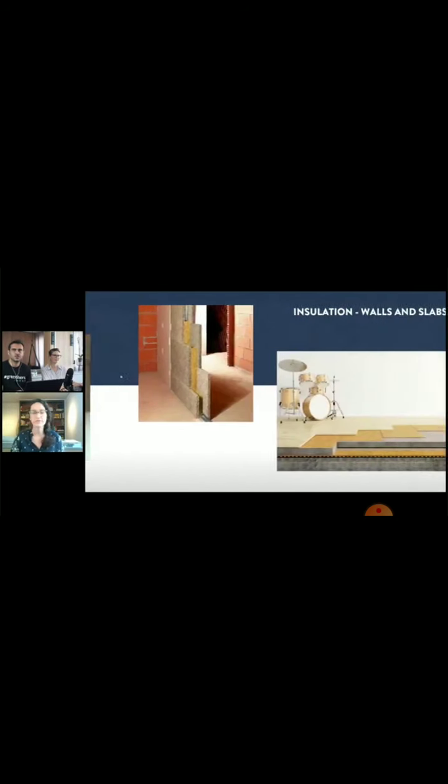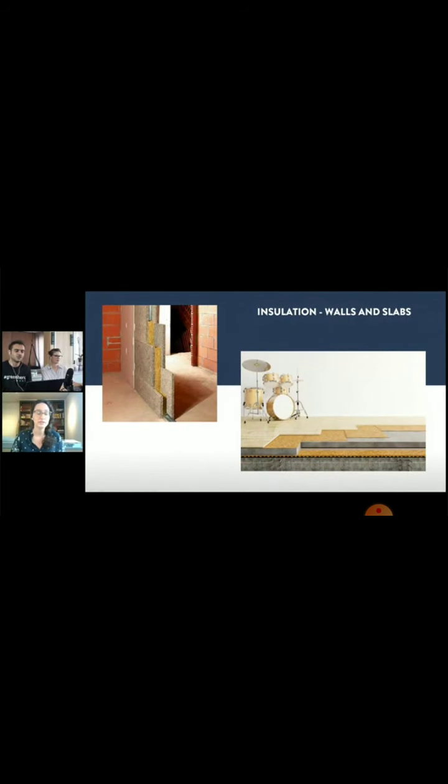We talked already about acoustic doors. Also, the thing about sustainable materials for slabs and walls is that when you have structural or impact noise, you need resilient materials. Sometimes sustainable materials don't allow that. They have to go back to their original form, which is hard to get. This is why those foams and rubbers do that. They go back, but they are not really sustainable overall.